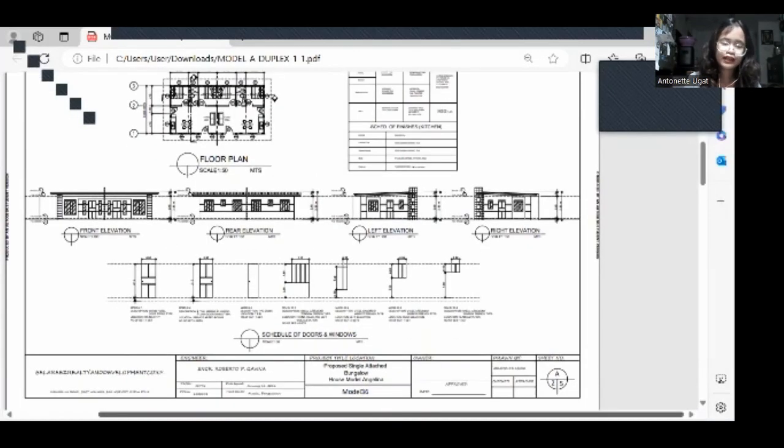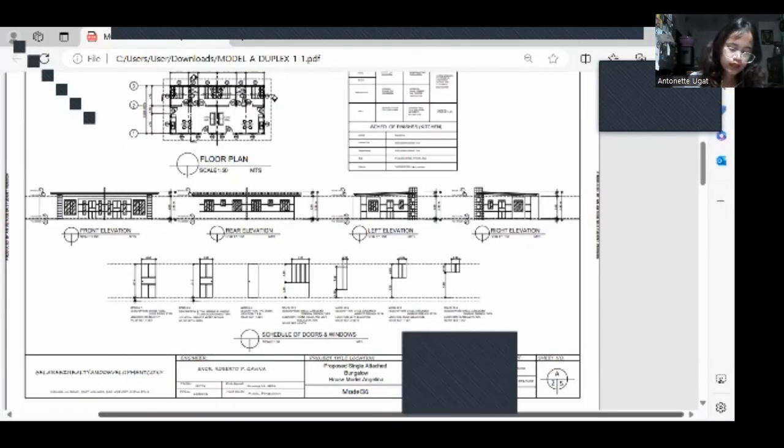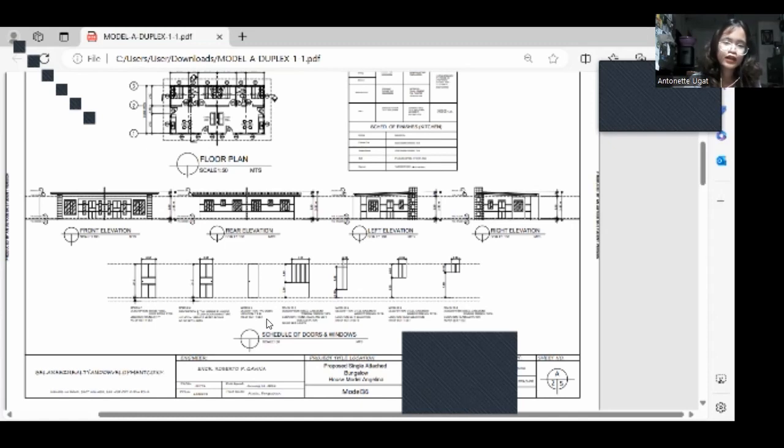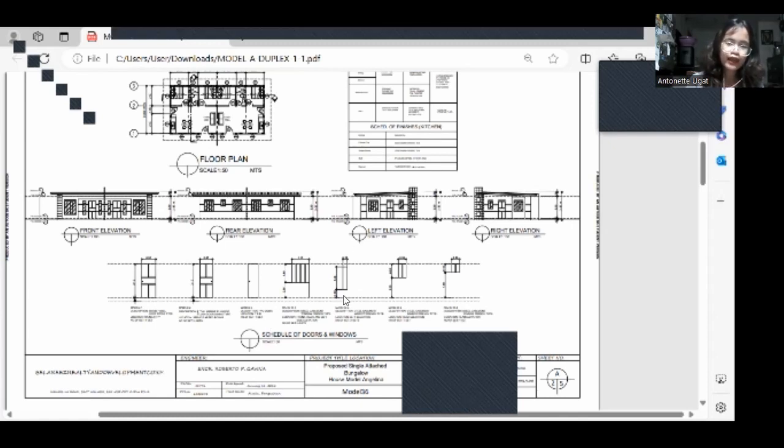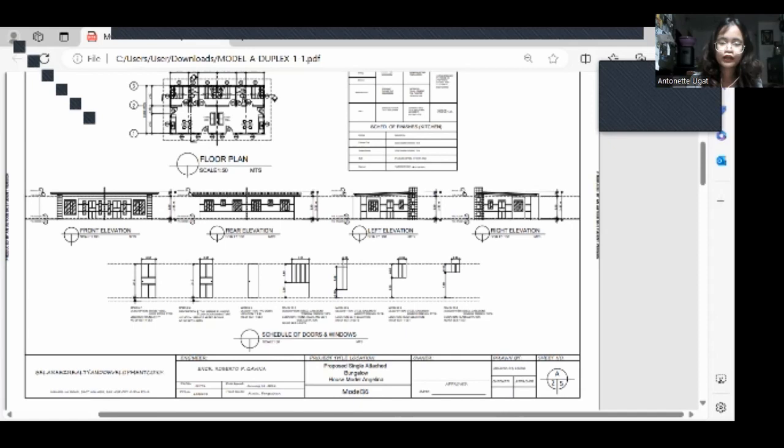We estimate that 1 gallon of latex paint is ratioed to 35 or 40 square meters, 35 for the exterior and 40 for the interior. So we got the area of each wall and ceiling and multiplied it by that ratio, 1 gallon over 35, and so we got the numbers here for the paint.